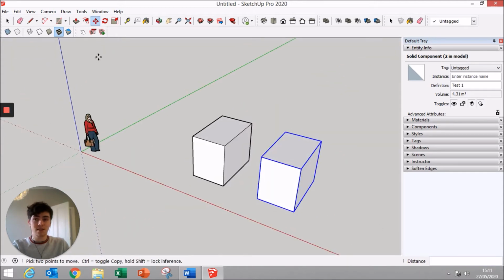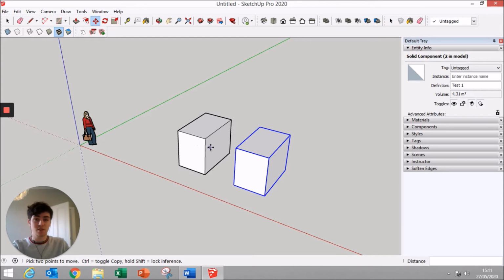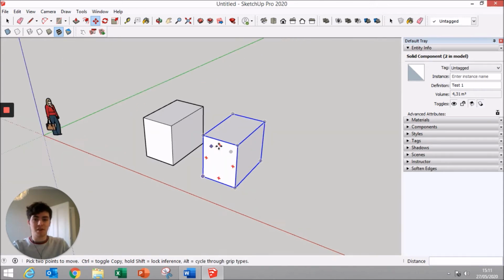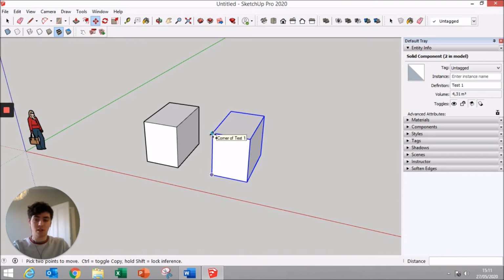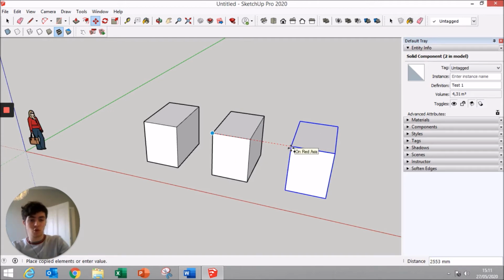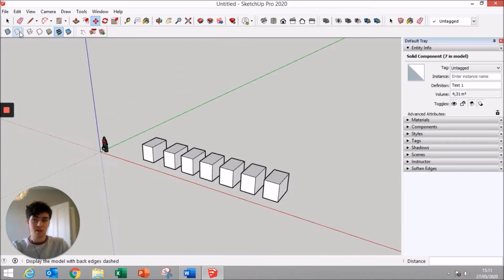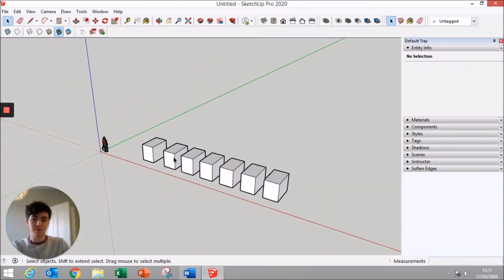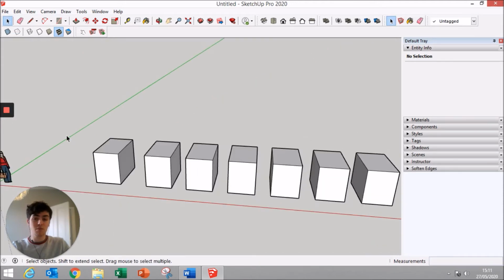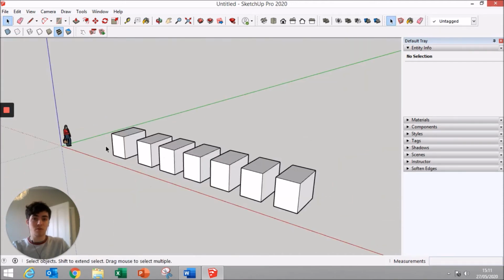In this case, if I want this component to be pasted, maybe 5 times, I'm just going to go there, keep pressing Ctrl, then move the object to the right, click, 2 meters as I just did before, and multiply it by 5 times. And here it goes. So you get 5 different copies of this component. That can be useful if you want to create multiple components.